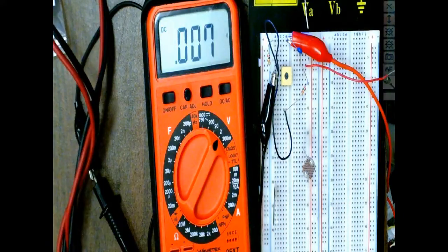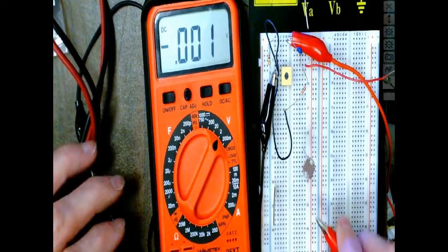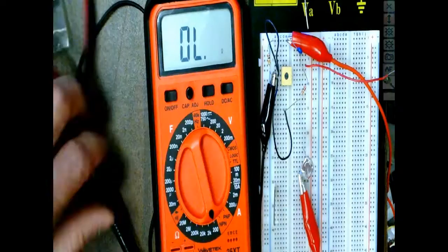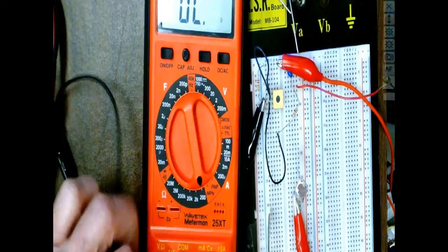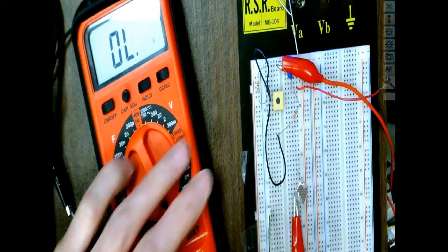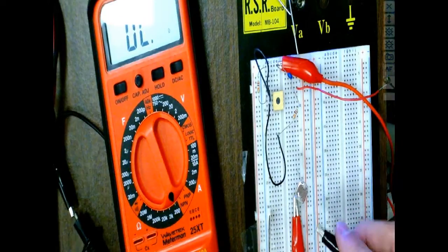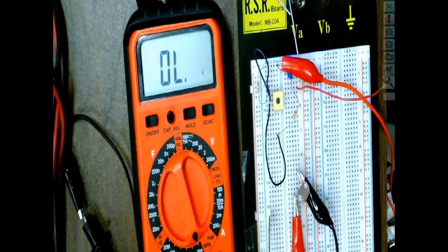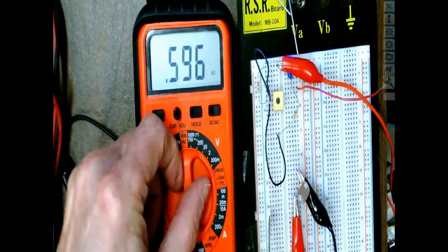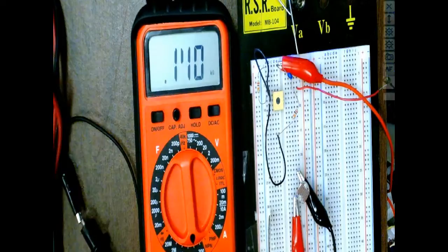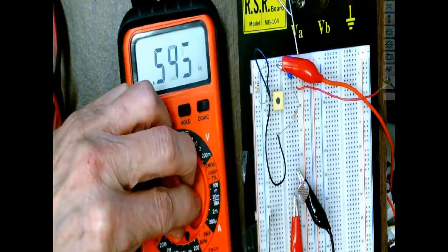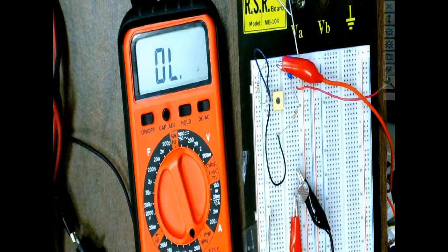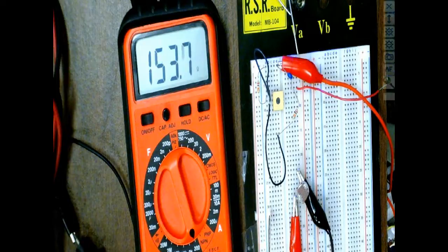And what this guy does is it varies its resistance with light. So I'm going to put my meter back on R, and we'll see what this guy does. I'm just going to take my meter and hook it across this thing. Right now it's showing an overload, so it's definitely got more than 200 ohms. Okay, now it started measuring. Of course, this is really going to vary. You can see this guy is already jumping around because undoubtedly it's seeing different levels of light.